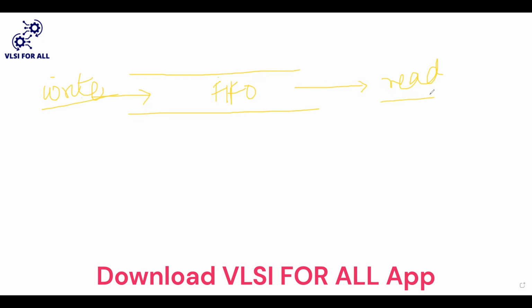the read signals. So then what will happen? Whenever the read clock is enabled, only then it should read, and whenever the write clock is enabled, only then it should write. So this particular thing is the asynchronous FIFO. This is one of the major applications in Verilog. Here we can observe that it is a synchronous FIFO, as the clock is one and the same.